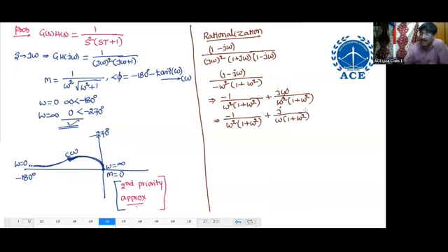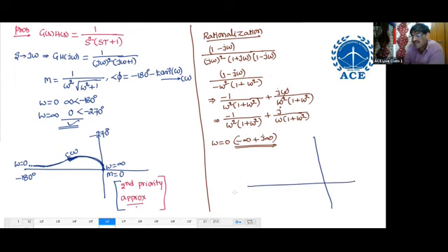Now tell, at omega 0: minus infinity plus j infinity. So that means x coordinate is infinity, y coordinate also infinity. Now draw the exact plot. Come on. Both are infinity only. But starting angle minus 180, ending angle minus 270. It should end here, omega infinity, magnitude 0.